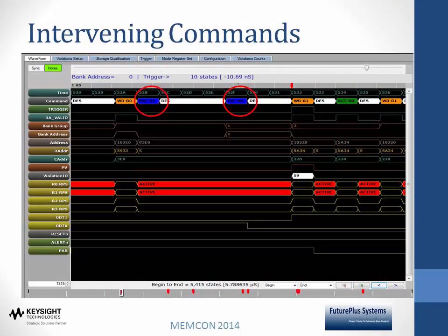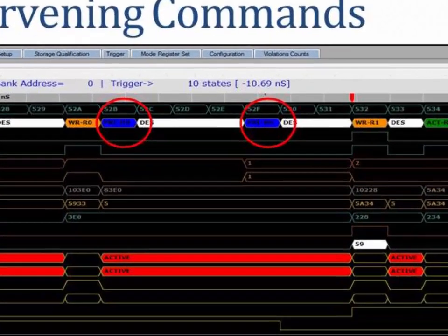In the previous slides, I showed how the DDR Detective can schmoo the latency values to determine where the system is operating. It can also trigger on those values and show exactly, down to the command and signal level, what is happening for this event.